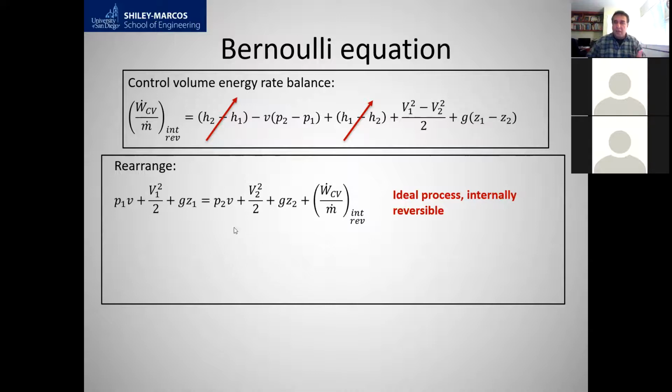We can use a U-tube manometer assembly to measure the difference in pressure, or we have a direct measure because delta P equals 1/2 rho V squared. If we know the velocity, we can find the delta P because rho is constant.